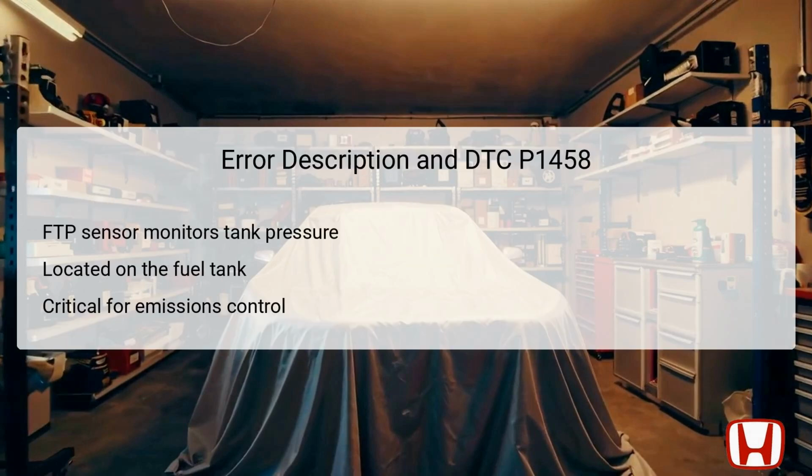The FTP sensor is designed to measure the pressure inside the fuel tank and communicate this information to the PCM. When the voltage or circuit range is outside the expected parameters, the P1458 code is triggered, indicating a potential malfunction. Located on or near the fuel tank, this sensor is crucial for ensuring that the vehicle operates within environmental regulations. Proper functioning of the FTP sensor prevents excessive emissions and promotes vehicle efficiency.